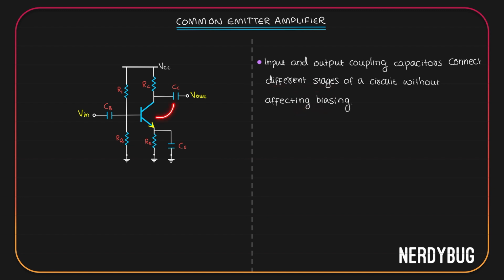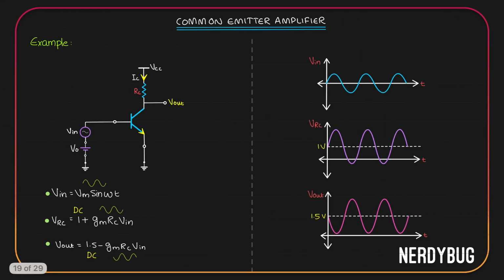See, in the circuit, I have applied the voltage divider bias. I would have carefully calculated all the values of R1, RC, RE, R2, CE, everything, so that my circuit is biased properly. Now, I am applying V input at the base. V input is probably coming from another circuit. We always consider V input to be sinusoidally varying. What if it has a DC value? Remember when we did this?